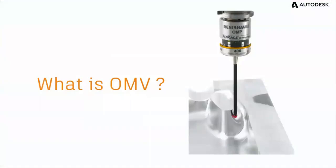Then what is OMV? If you talk about OMV, on-machine verification, it's simple logic: if you have any VMC or HMC machine, you don't have to remove the part for inspection to the CNC inspection section. So it can be inspection on the machine itself, right? If you have a VMC or HMC machine, you need to attach a touch probe.